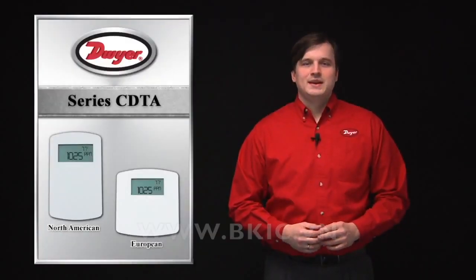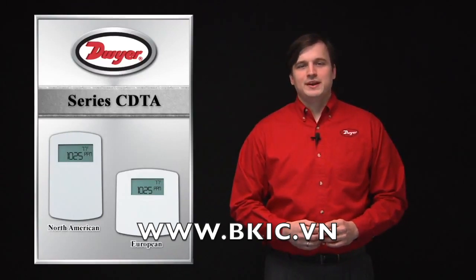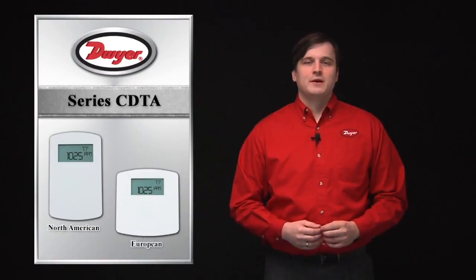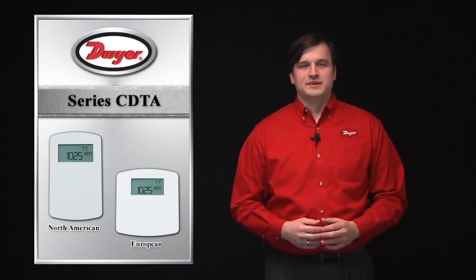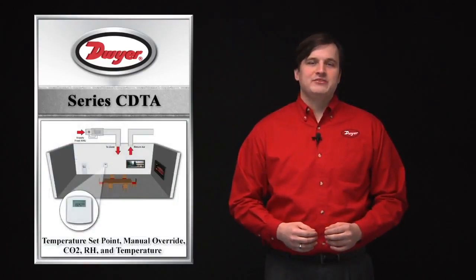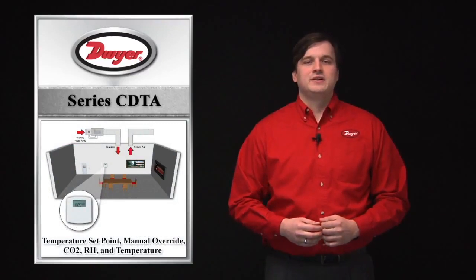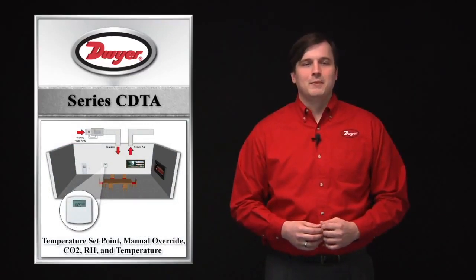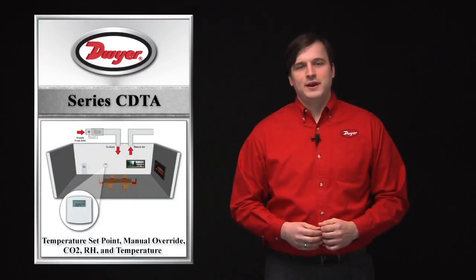The third product series is the CDTA. In this series, temperature set point and manual override features are available in addition to CO2, RH, and temperature measurements. Here, all of the measurement and user setting values are communicated via BACnet or Modbus over an RS-485 connection.